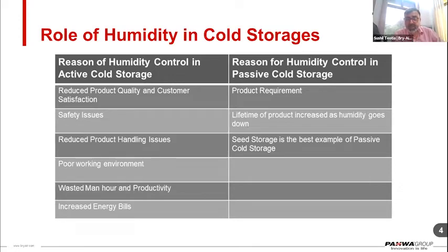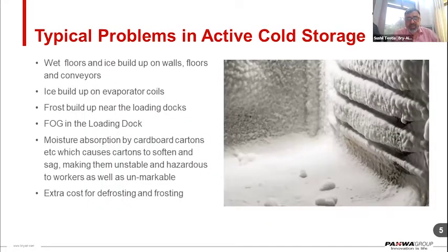There, the storage time is generally very high because these are seasonal crops which come in and we have to maintain them for a long time as per the market requirement. Generally, what we observe in the market for cold storage, the way we are currently operating, is that people experience a lot of wet floors and ice buildup on the walls. That is primarily because of the excess moisture present in the air inside the conditioned environment, and that is damaging the entire setup.